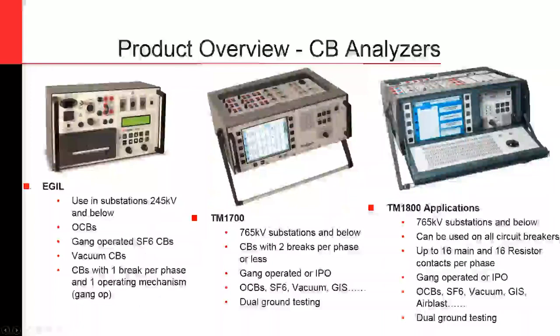And one of the unique features of the TM1700 is our ability to do DCM dual ground testing and measure a breaker with both sides grounded.